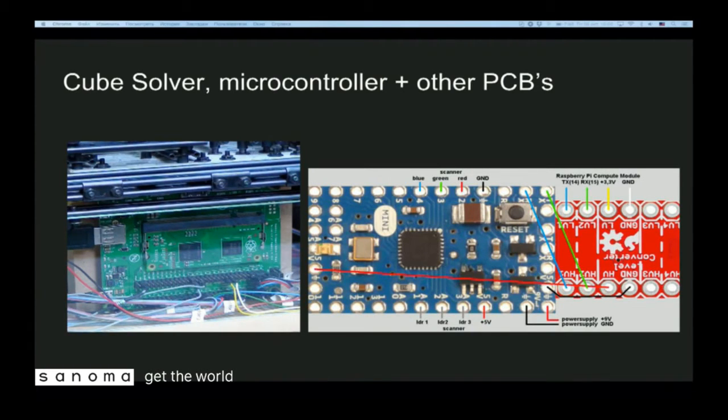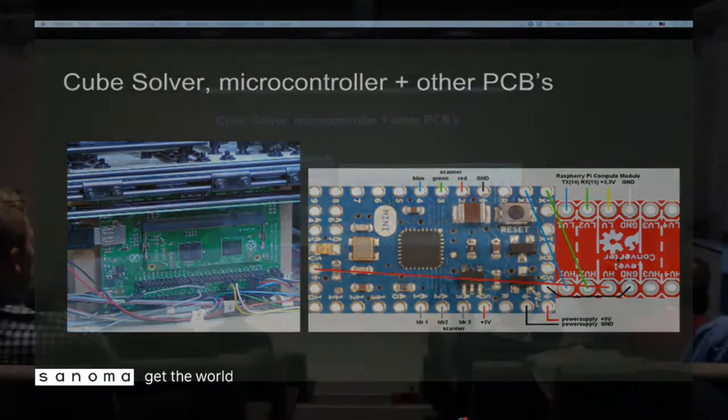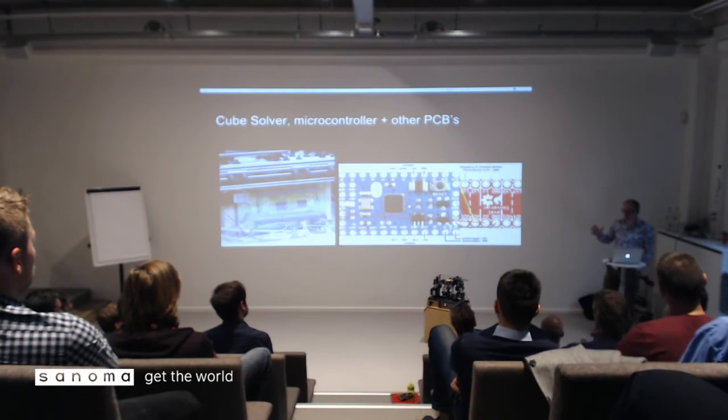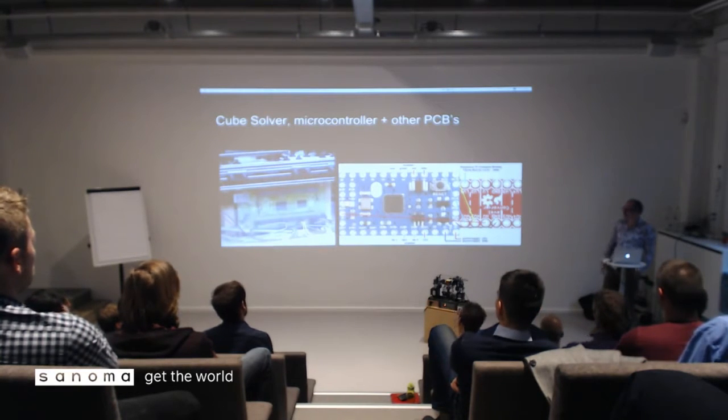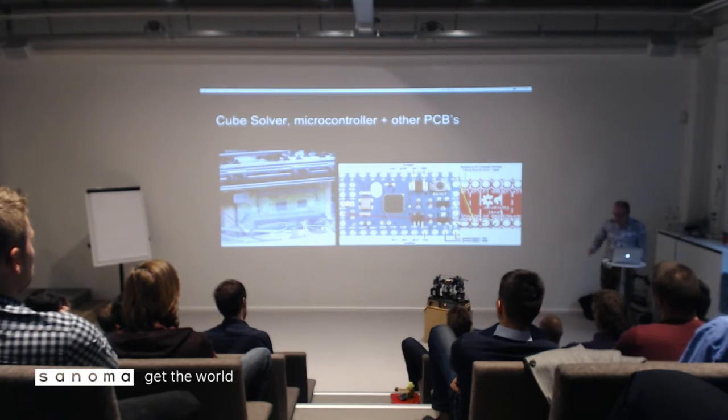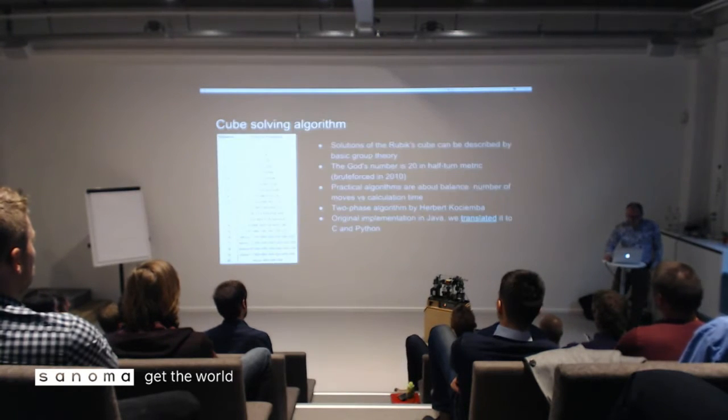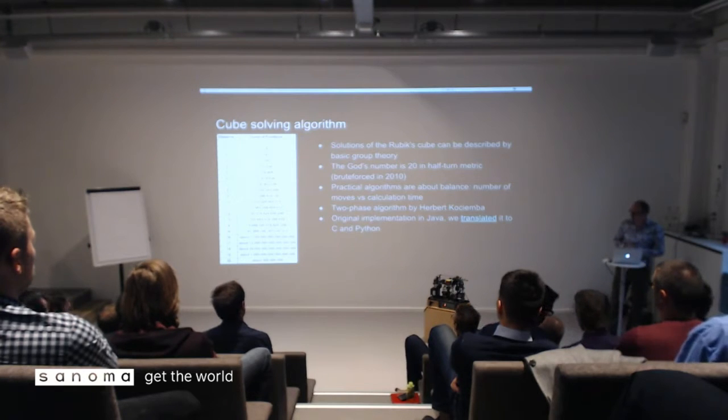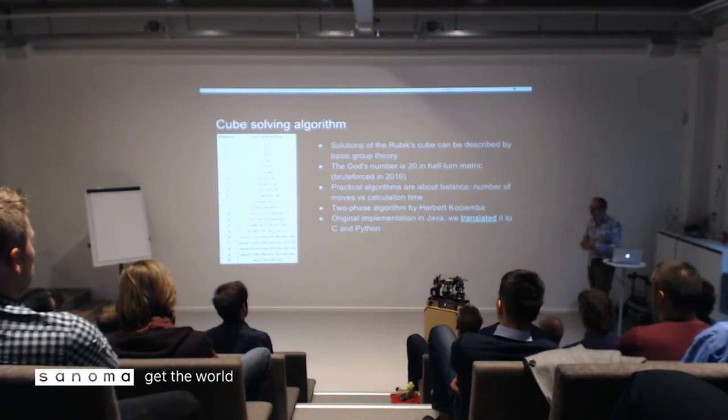The Raspberry, as you know, can only work with digital GPIOs and signals, and the Arduino Mini can work with analog inputs and outputs. And therefore we needed this logic level converter. Actually the machine is nothing without any programming. That's just a bunch of cold metal.